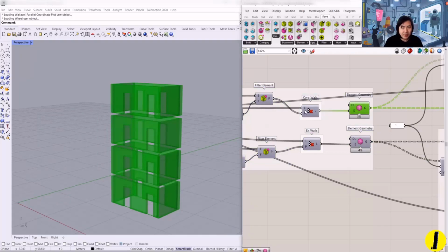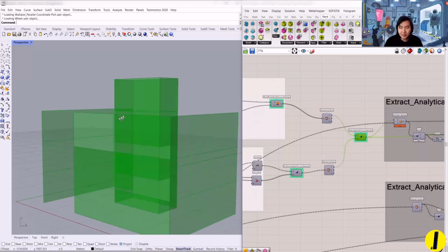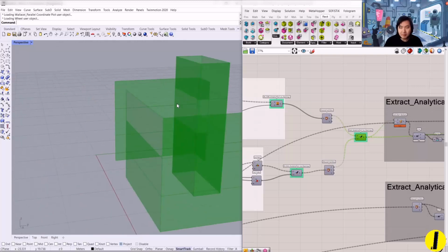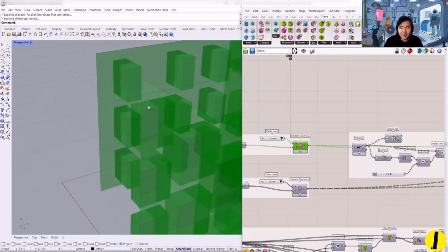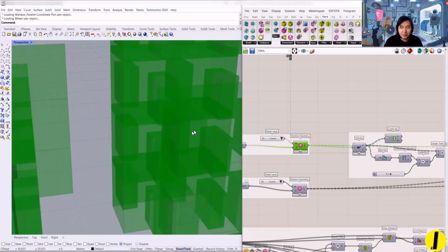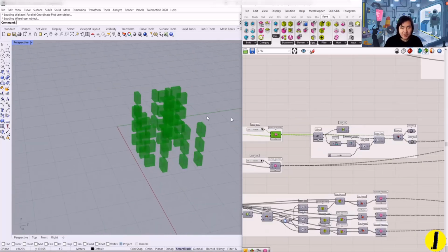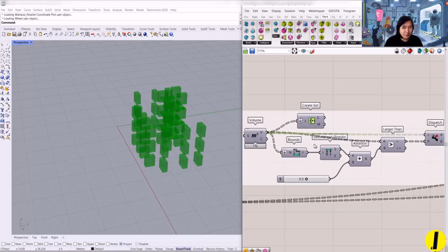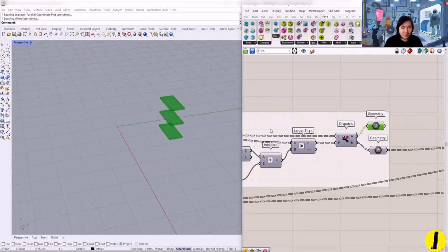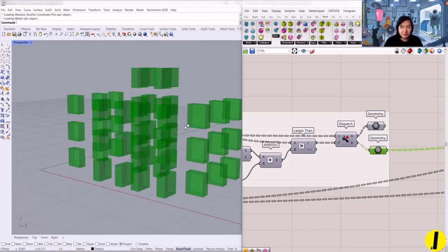You remember we extruded here, we have these plane extrusions, and we're going to use the openings to subtract openings from the analytical model. That's why we have these generic models, and we just filter them by volume size, because we don't need the floor openings to subtract. We just need wall openings to subtract from the floor surface.